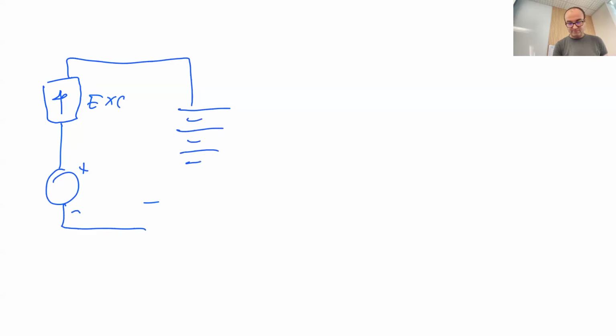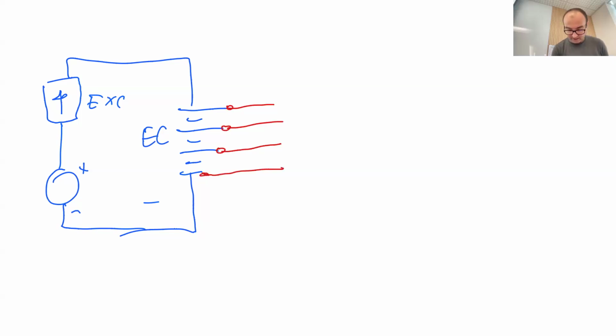I'm drawing it as a battery because I would like to see it as a stack, although it is an electrolyzer. So we are measuring voltages on each of these cells. There are 20 of these, and we have this flux gate sensor here as a 21st channel.